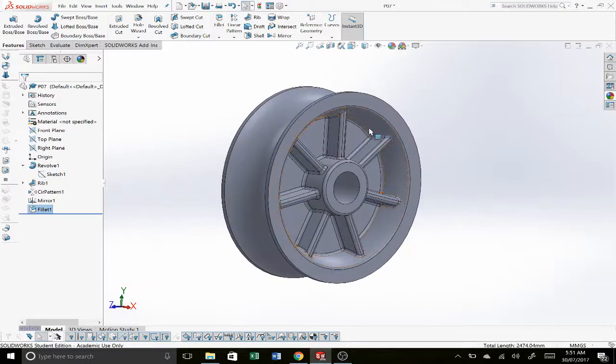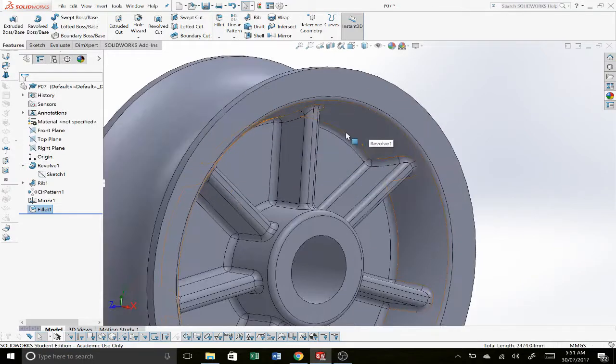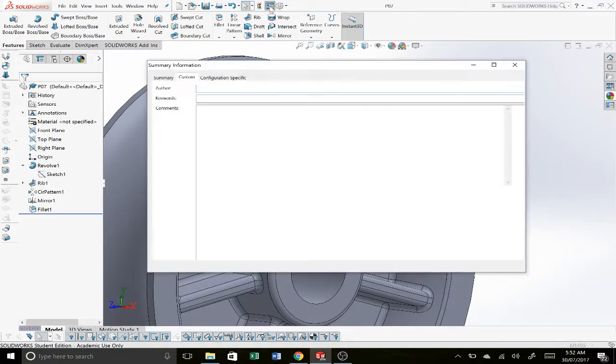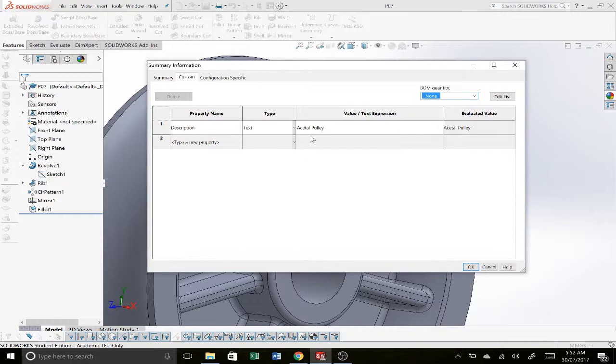The reason we have these fillets down the bottom is for the way the machine would typically cut the tooling. It would use a rounded ball bearing tipped type of tool. And we'll go over that a little bit in class. You can ask me about it again if you want more detail about tool manufacturing and that kind of stuff. So we'll hit save. We can see it's P07. Let's just double check our custom properties. We can see it's set to Acetal Pulley.